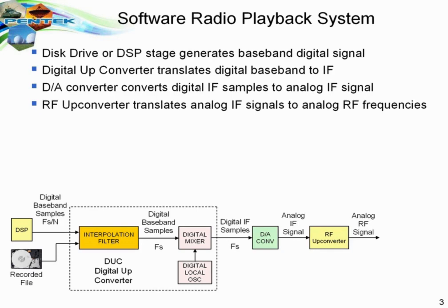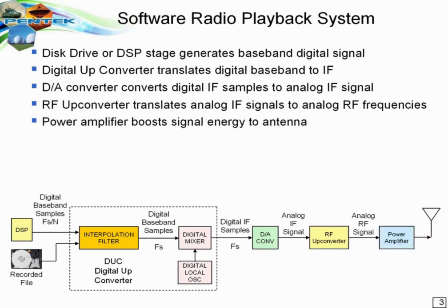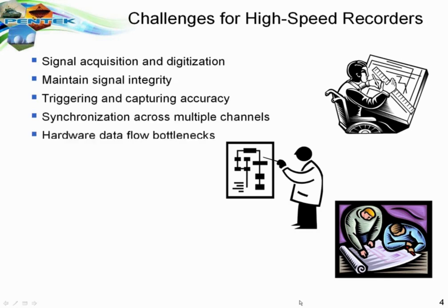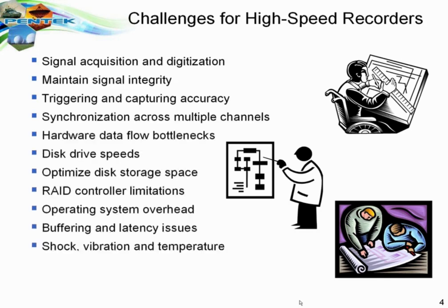The rest of the system must be a very high-performance server-class PC or single-board computer with fast links. It needs to have a reasonably fast CPU. It has to have very fast memories and bridges and chipsets that allow the PCI Express links to connect this board to the memory and to other boards such as the RAID controller, which is the interface to the hard drive. So we're using PCI Express Gen 3 often in the system motherboard, and we're using SATA 3 disk interfaces to achieve the rates that we need across the system.